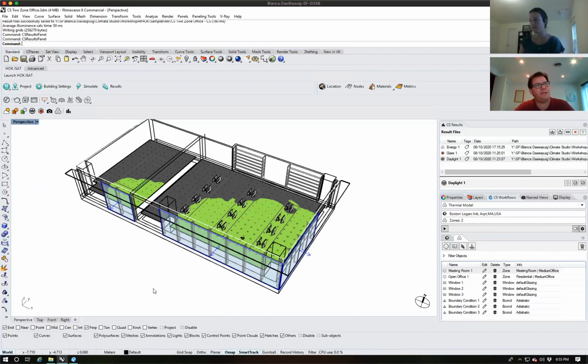And then you mentioned that later on in your workflow, as the project moves into later phases, you'll actually bring Revit geometry in. I guess you create a new model based on the Revit, or do you just remove? No, I just import the Revit model. I export it as a DWG, and then I open it in Rhino. And the only thing is, if you were to work in Honeybee and Ladybug, you would have to rebuild it because it would be very heavy for it to run, or at least that's been my experience in the past 5 years.